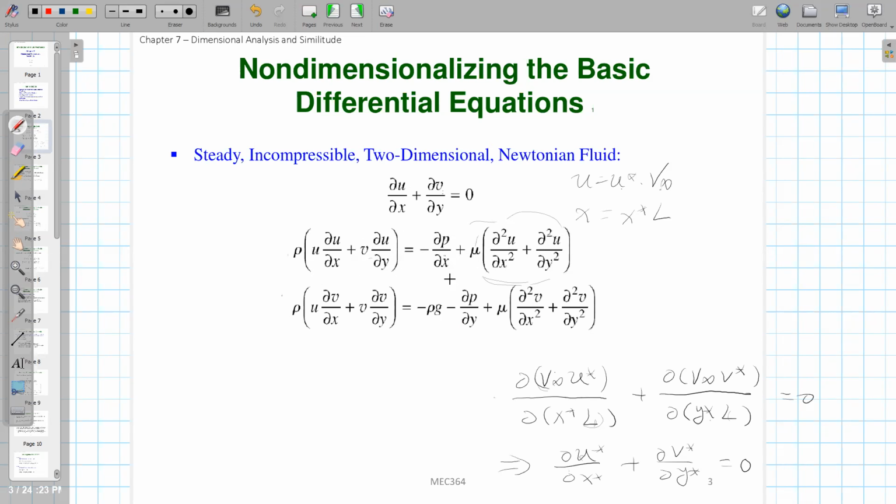You won't be able to see that very explicitly from this dimensional form. Why? Because these are dimensional, they each have their own unit. You cannot just determine whether this term is bigger or smaller simply from this mu parameter. Even if this mu is small, after mu times the second partial derivative of u with respect to x, maybe the velocity gradient is large, and so overall this viscous term is still large. So you won't be able to know whether this viscous term is significant or can be neglected if you only know mu.